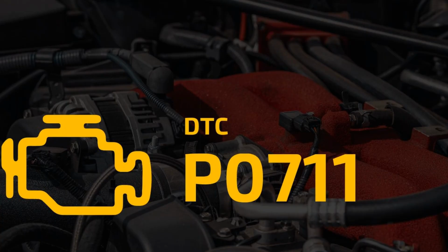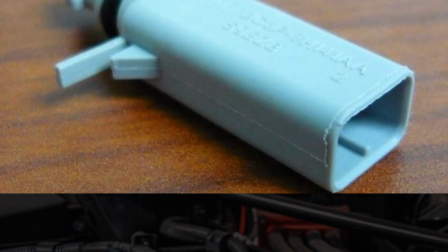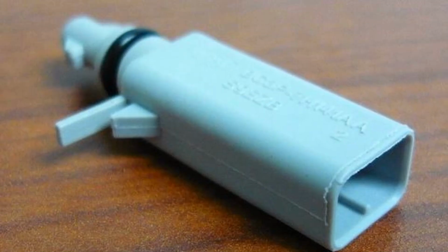If the code returns, we will have to test the TFT sensor and associated circuits. Wiring test: with the ignition key off, disconnect the electrical connector from the TFT sensor. Connect a digital voltmeter, the black wire to ground and the red wire to the signal terminal on the TFT sensor's wiring harness connector. Check sensor: connect one ohmmeter cable to the signal terminal on the TFT sensor and the other cable to ground. Check the resistance according to the manufacturer's specifications.